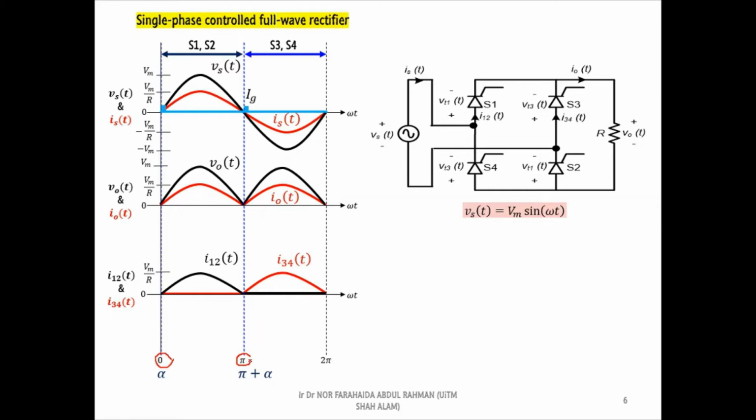As you can see, all voltage and current waveforms are similar to the voltage and current waveforms of uncontrolled rectifier with resistive load. Next, I will shift the control signals to the right. Due to the new firing angles, the conduction range of each thyristor reduces.